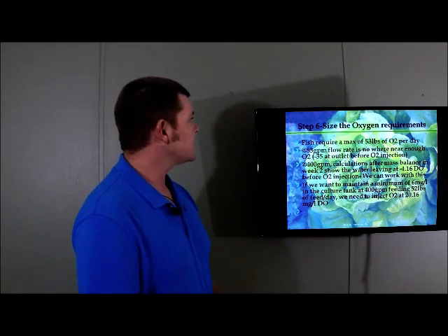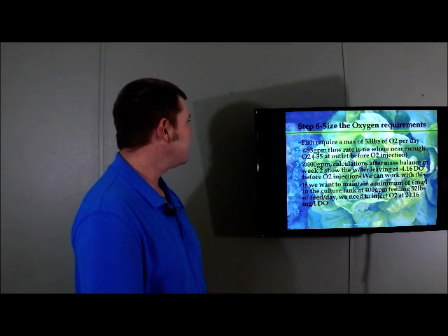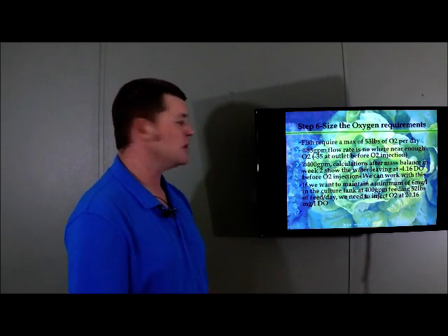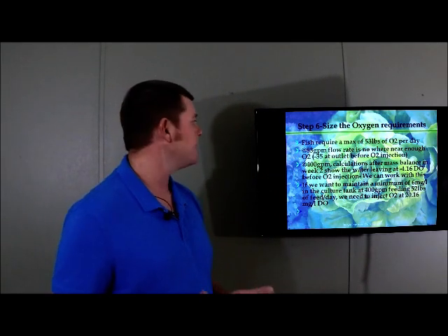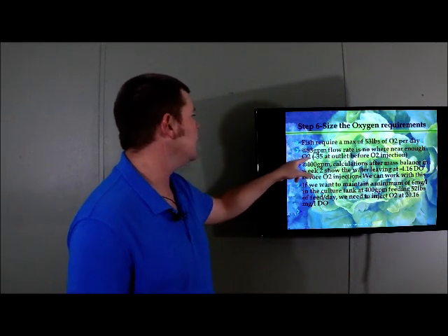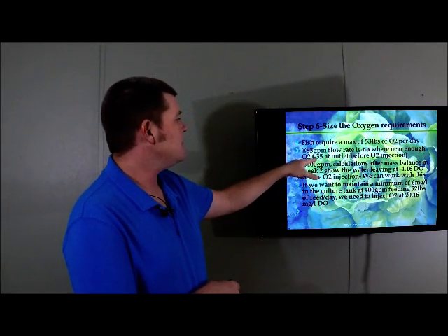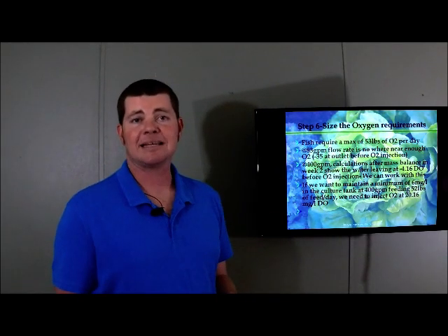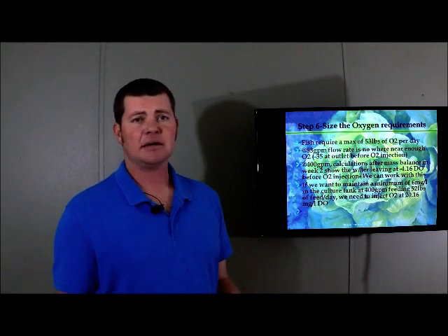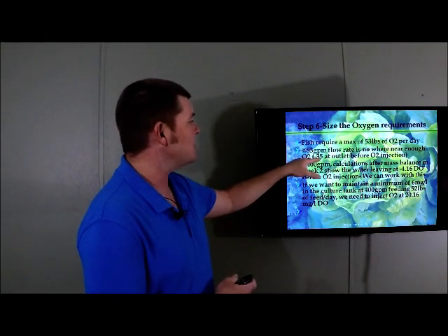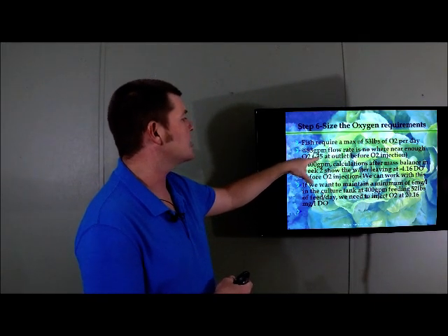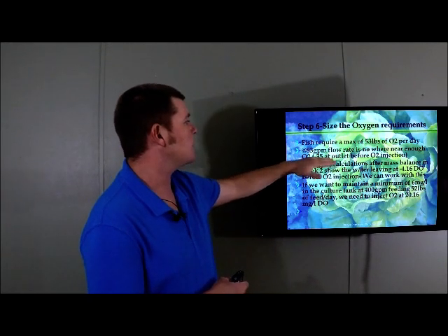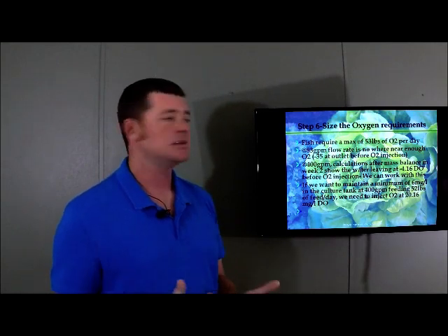The fish require a max of 53 pounds of oxygen per day, and that's at 83 gallons per minute flow rate, which, if we were to turn that tank over 1 time per hour, is nowhere near enough oxygen. Okay, we would have negative 35 DO at the outlet before we inject any oxygen in the tank. So that right there tells us we would have to achieve a very high oxygen saturation level to get where we want if we are going to be at negative 35 before adding any oxygen to the tank.